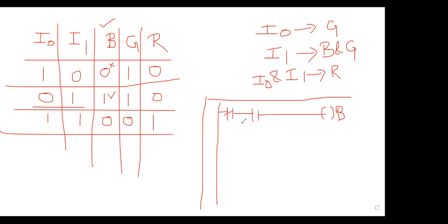So you have taken I0 and I1 here. One person made the mistake that he took only NO. We have to take NC also here, correct? Next, check blue again. Blue, blue, blue, it is done. So blue is finished. Now I shift to green, but what have you done? Some people, as they made this, they were seeing this also, and they made a series-parallel connection. That was the problem. So when you make for blue, make for blue only, don't think about green.